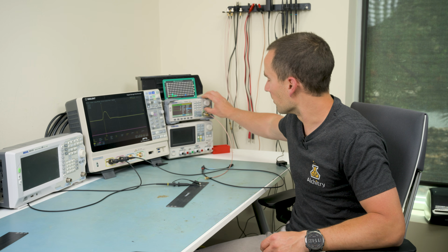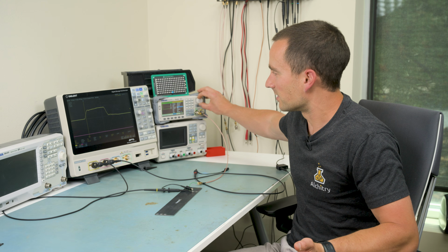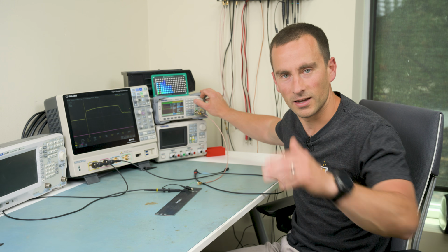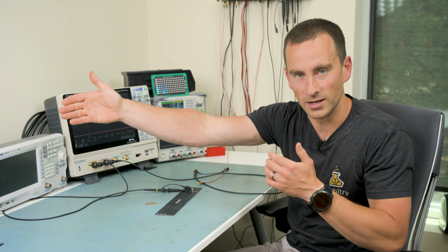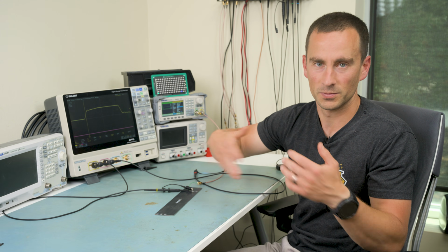And if I make the pulse a bit longer, you can see that it stays clean. We don't have any of that weird stair-stepping effect from the reflection hitting the end, coming back, and then going back and forth. There are actually two ways we can deal with reflections. The first one that we just did is known as parallel termination. This is since our termination resistor connects to the transmission line in parallel.